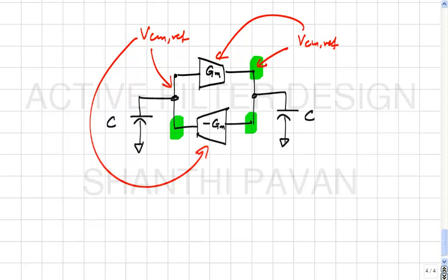So then the next argument is, why don't you use two types of transconductors, where the input common mode voltage is higher than the output common mode voltage, and use another kind of transconductor where the reverse is true. Then you can put them in a loop and both will be happy. You understand? It's generally a mess to do. Unless there's some very specific reason to do so, it just makes life more miserable than it already is, and you don't need more miseries. You understand?